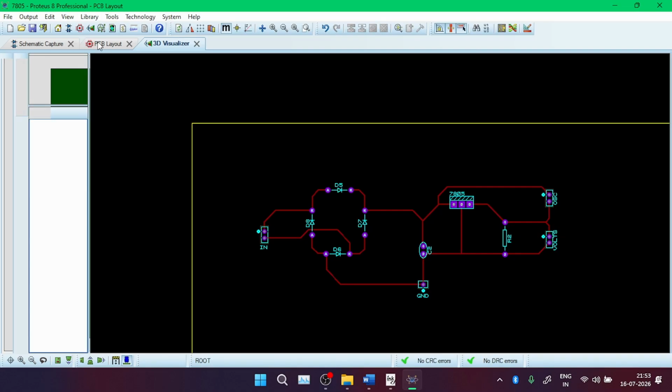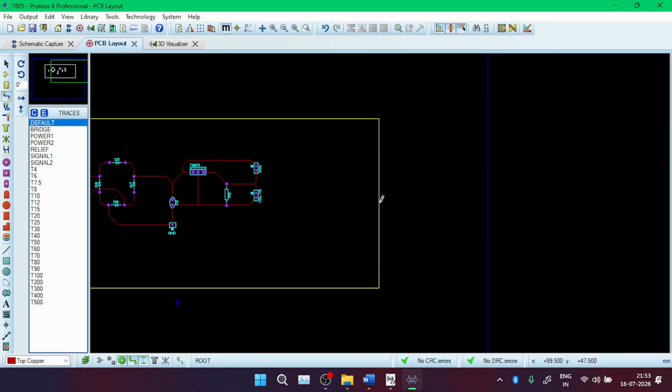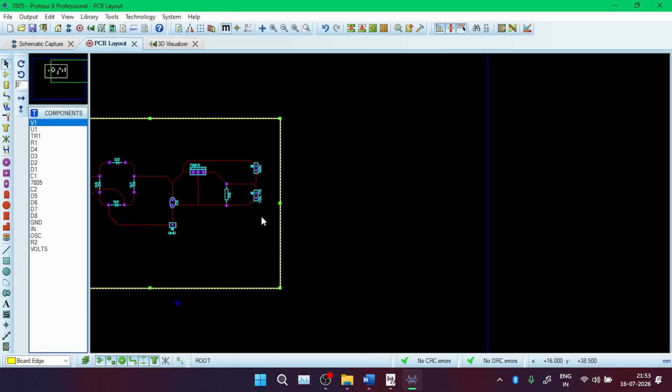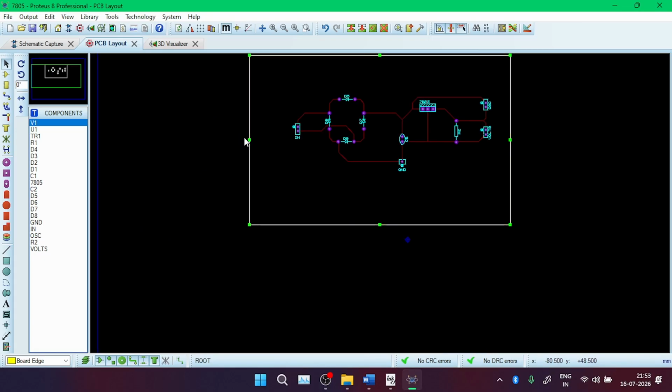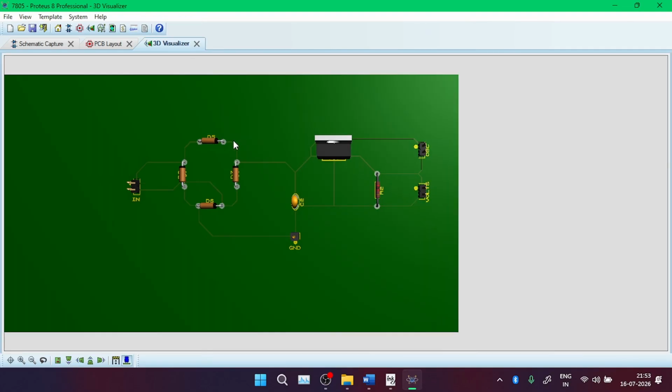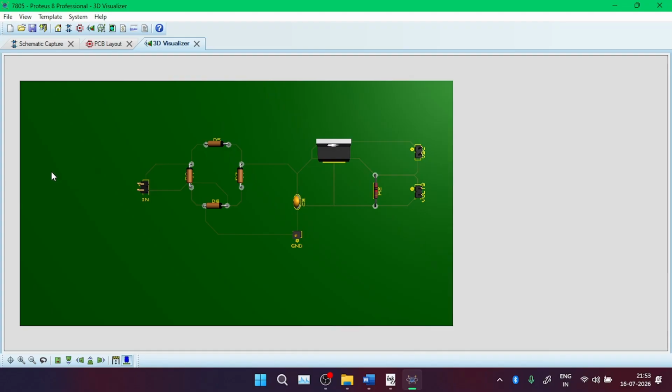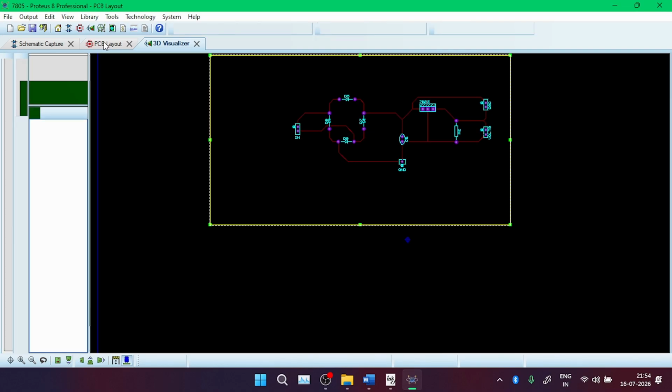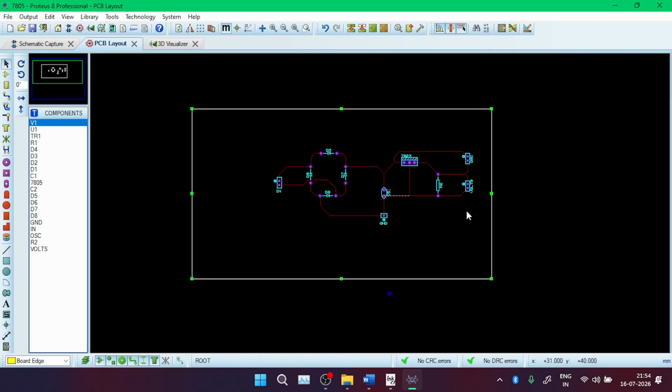And in order to reduce the board, I'm going into the component mode, selecting the board, and resizing this like this. I'm going to increase this so that I can place a transformer here itself. I'm going to fix it with screws, and by using jumper cables I'm going to keep it here. Now, this is the complete virtual part of creating your PCB, your printed circuit board.